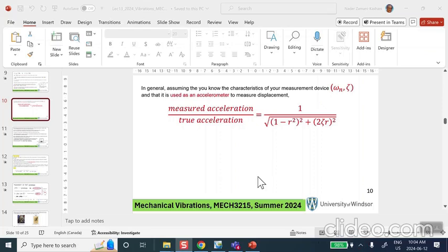It gives you a voltage that's proportional to the displacement, relative displacement. So in order to find the measured acceleration, you have to take that data multiplied by natural frequency squared, and the requirement is that, of course, you know the value of omega n. Also remember that the damping ratio has an effect, and the optimum one that I showed you in those graphs was 0.7.